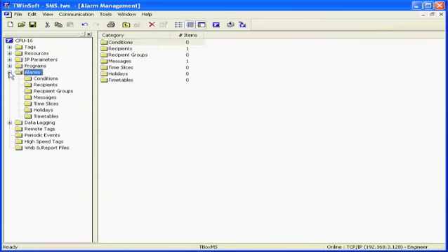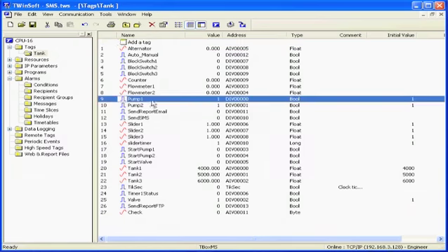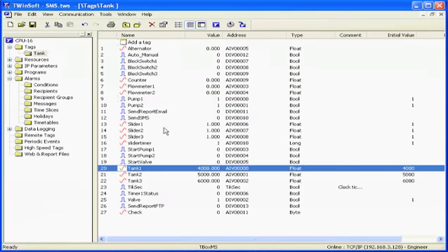Alarms are configured in TwinSoft from the folder Alarms. But before we go to the alarm configuration, I would like we take a look to the tags. The tags correspond to the event that will generate the alarm. It can be an event linked to the process, for instance a pump changing to 0 or 1. It can be a tank level reaching a min or a max level.